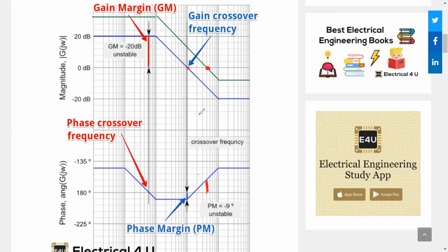Just notice that if you want to actually draw conclusions about how your controller will behave, just plot the new Bode plot after the controller is applied, and see how the margins look after that. Don't just trust the original margins, because that can lead into trouble.